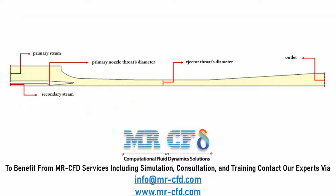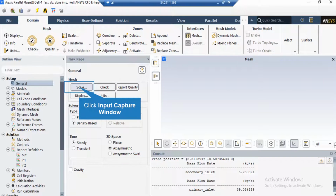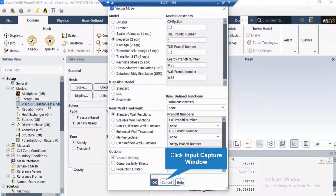The present model is designed in 2 dimensions using Design Modeler software. The meshing of the model has been done using ANSYS meshing software, and the mesh is structured. Under the General Setup tab, you can see different buttons from scales to units. In the present project, the realizable k-epsilon model has been used to solve the turbulent flow equation, since it is more accurate than the standard k-epsilon model.